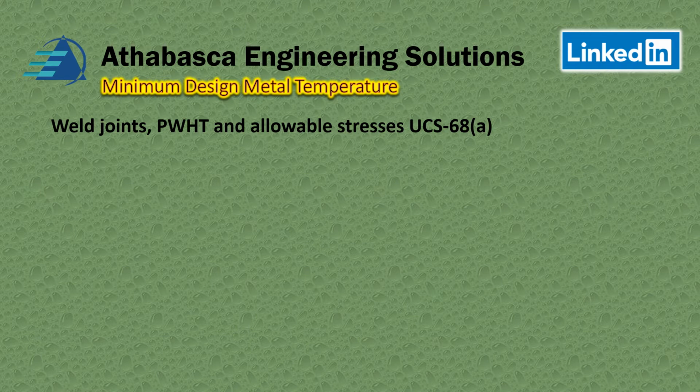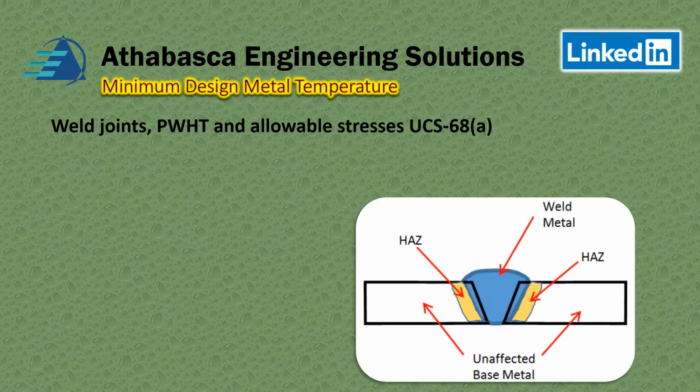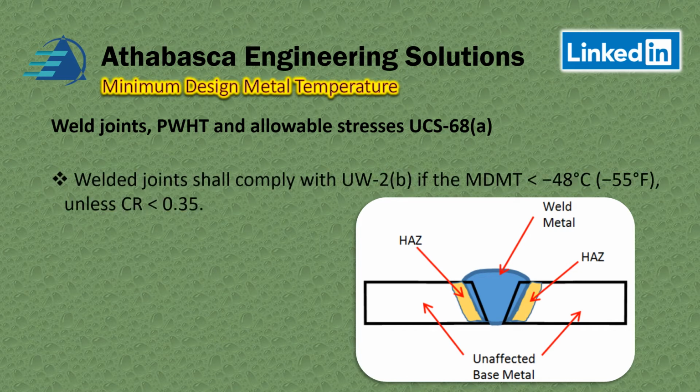So the first part is, this is your typical weld joint, and it says that the welded joint shall comply with UW-2B. That's a criterion if the MDMT is colder than minus 48 degrees centigrade or minus 55 Fahrenheit, unless the coincident ratio defined by UCS-66 is less than 0.35.